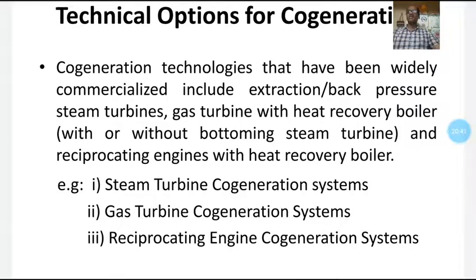Heat exchangers are installed to recover the wasted thermal energy contained in the exhaust gases of the gas turbine, of the internal combustion engine or the steam generator, in the bleed steam or exhaust steam of a steam turbine, in the cooling water of the internal combustion engine jackets, or the lubricating oil and in the turbocharger.